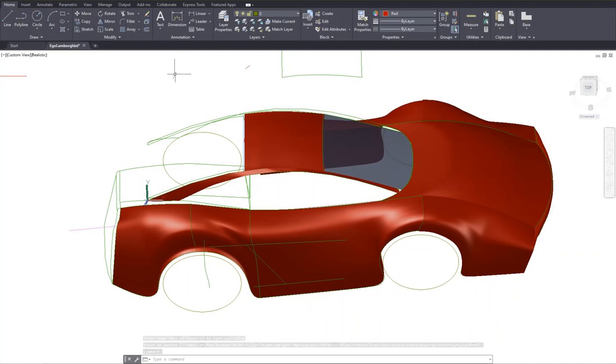All of the surfaces, we call them mesh, or AutoCAD terminology for the surfaces mesh, and we convert them into solids so that we can 3D print them. Initially, we can create those surfaces, inclined surfaces, all of them curvilinear surfaces, but as a mesh, and then we use the thicken command and convert them into 3D solid models. Finally, with the expectation that we're going to 3D print this, if it's a solid model, it will be 3D printed, and meshes are not normally 3D printed.